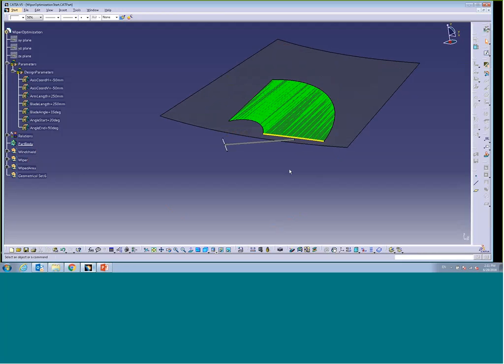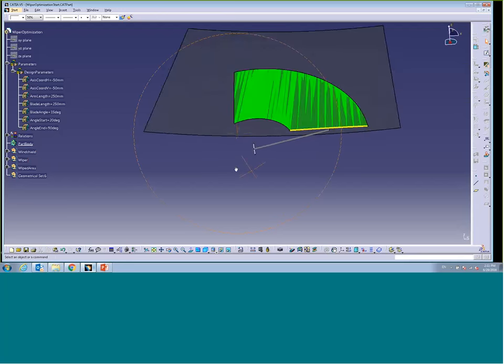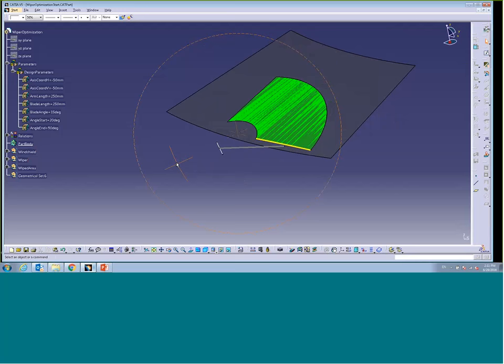So I got the axis of rotation. It's a kind of one blade design. The windshield is sort of narrow a little. So I'm going to try to see if I can come up with a good design just using one arm. So here's the blade, the yellow one, and this surface, the green one, represents the wipe area. So the model has to be parameterized. So what I've done here, I've created some parameters that control the geometry of the setup.